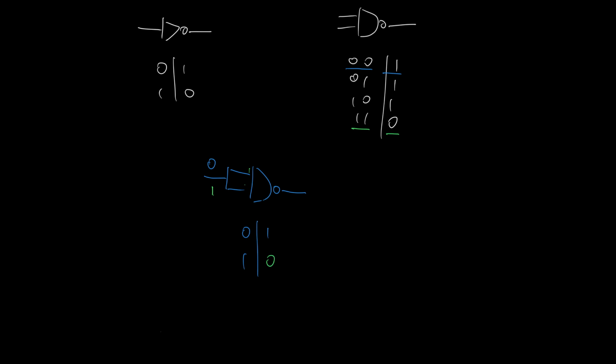And we saw before that I can swap inputs around by using inverters at the input. And so that suggests, to me at least, that I can take both inputs and put them through inverters. Because then if I've got 0, 0 coming in here, after that goes through inverters, I'm going to have 1, 1 coming out here.